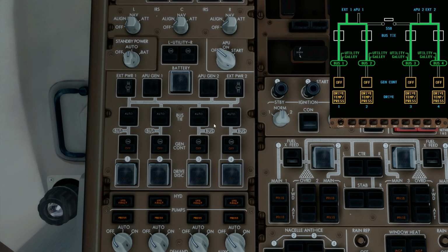Okay, so on the ground, the AC power is provided by 1 or 2 APU gens, or 1 or 2 external power sources. Back to that synchronous bus for a second. There's actually a split system breaker in the middle of the synchronous bus that can open and close automatically, depending on how many auxiliary power sources are connected. So when one source is selected, the breaker closes and powers both sides of the synchronous bus. And if both sources are selected, then the breaker opens and isolates the right-hand side from the left-hand side.